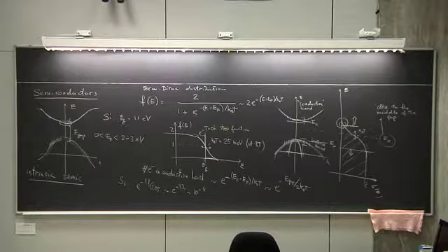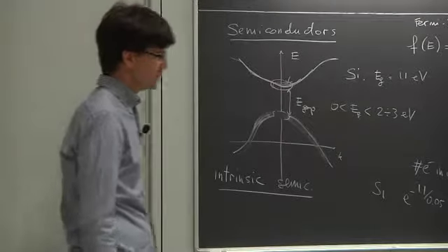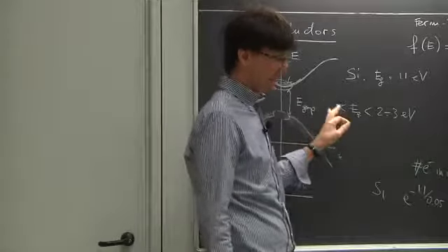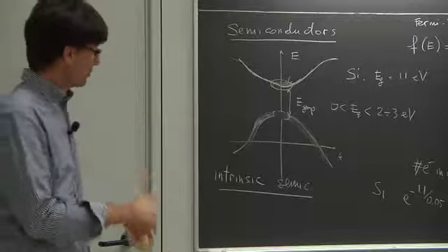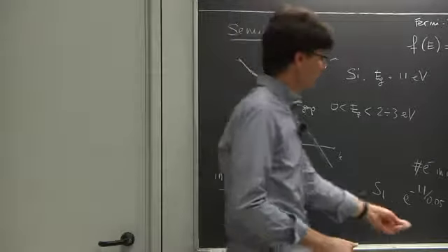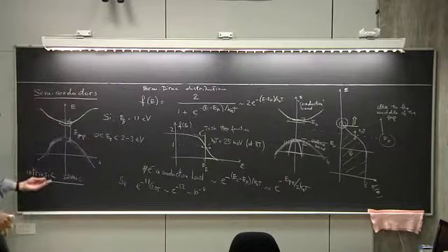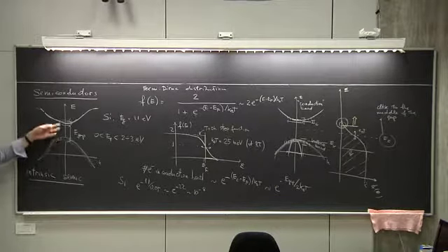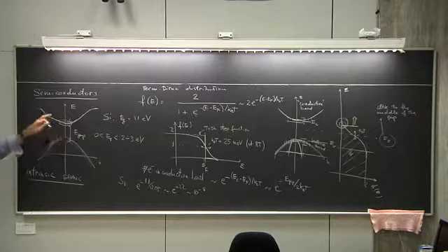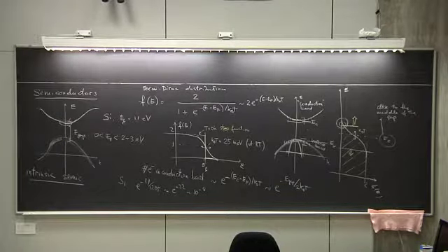No other change to the system from the perfect crystalline state. So the conductivity that you measure here would be extremely small, and it's called the intrinsic conductivity, because it's due to the intrinsic carriers, the carriers that are excited just by thermal excitation across the gap due to the Fermi-Dirac distribution.